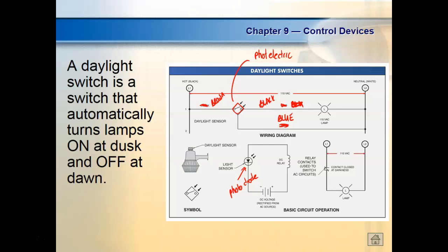if it's an AC sensor, the brown and blue doesn't make any difference. But you need to follow an industry standard to understand, because that way, if it was a DC sensor and you look at it backwards, you look at another one over here, it would go wrong. So AC, brown and blue wire makes no difference. But DC, if it's a DC sensor, it's very, very popular now.